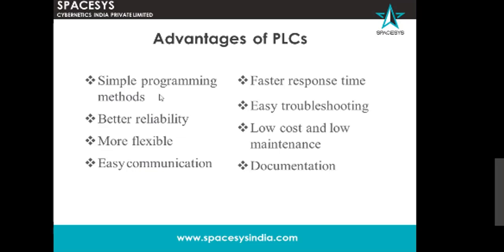Other than this, PLC has many advantages. Better reliability. It has a longer life compared to traditional systems. The internal relay system of a PLC is solid state, so its function is not mechanical like conventional relay systems. It won't wear out as fast as conventional relay systems, as it has electronic solid state relays. And it is more flexible. One single PLC can easily run many machines. Adding inputs and outputs can also be done easily just by connecting the extension modules, and this makes PLCs an easily expandable device.